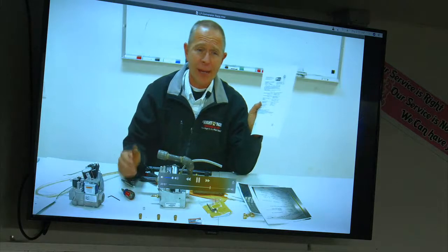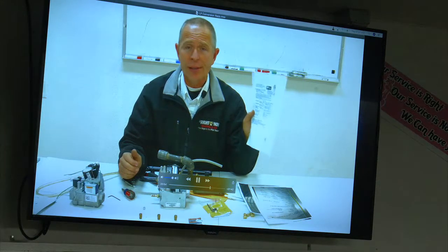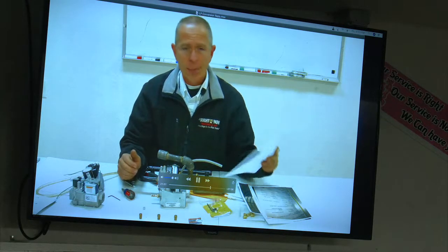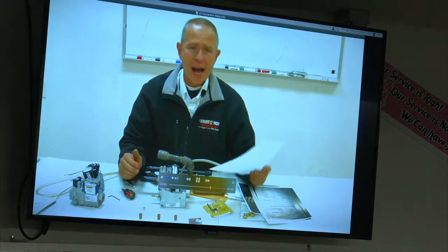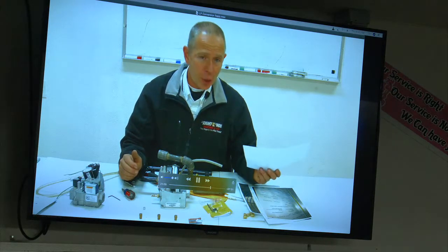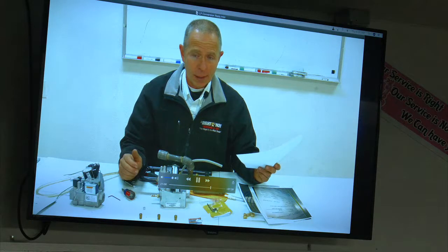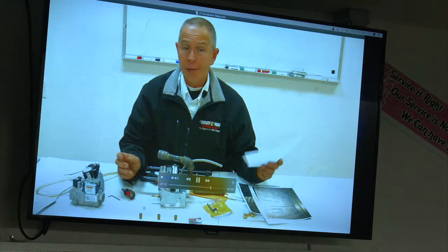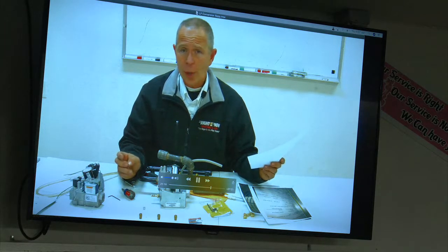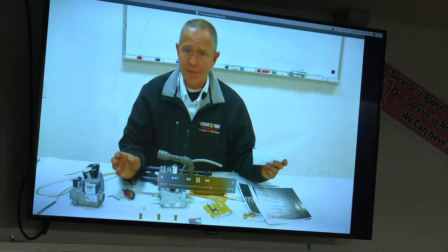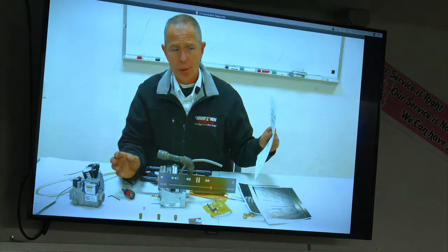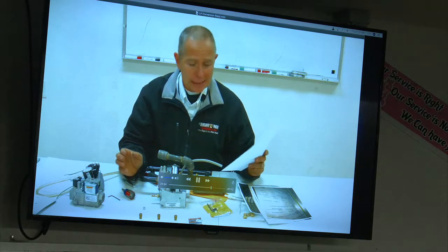In other words, after about 3 minutes or so, the heat exchanger and all of that should be up to temperature. If it's extremely cold, it might be 5 minutes. But this is how we do this. We find out what the incoming air or the return air at the unit is. You can use the thermostat, but if there's a leak in the return or something, so by the return, by the filter, as close to the unit as you can, you want to get your return temp.